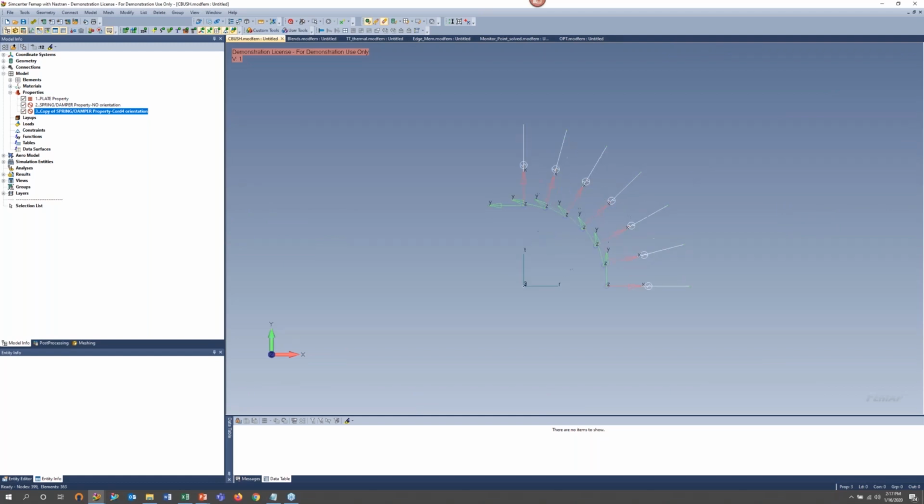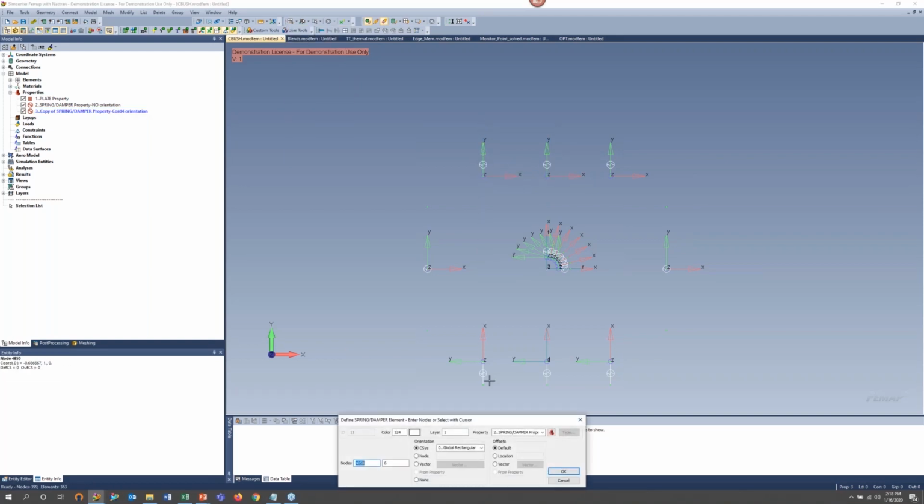In this case, if I cared about this direction, I could define their X stiffness, or K1 stiffness, in that form. But in some case, maybe I didn't define this one correctly. Maybe I needed to reference something else. I could always edit that element, just grab this one. Actually, I wanted that to reference a different coordinate system, or I wanted to specify it with a node or vector. However I wanted to define it, I could go ahead and define it.